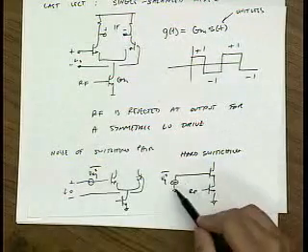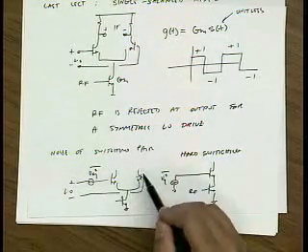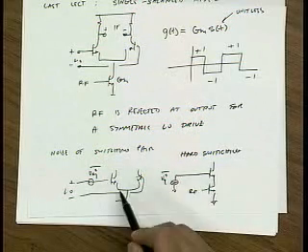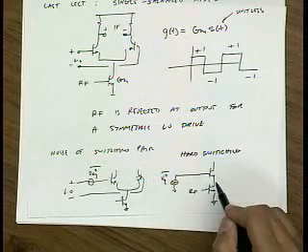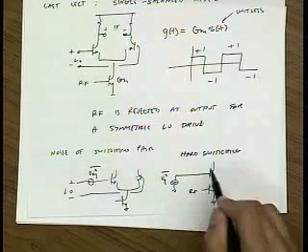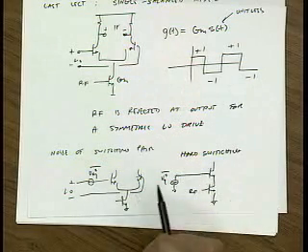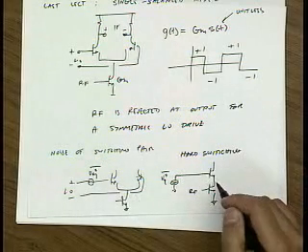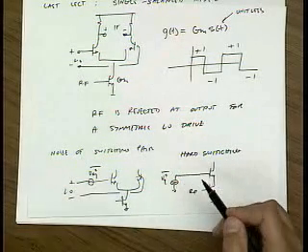That this V equivalent essentially looks like a cascode circuit because this device is turned off by the hard switching action, or vice versa. And as we studied in LNAs, cascode configuration will reject the noise of this device, right? So the noise is rejected by 1 plus GM RO of the device. So the noise to the output is actually very low due to this device.